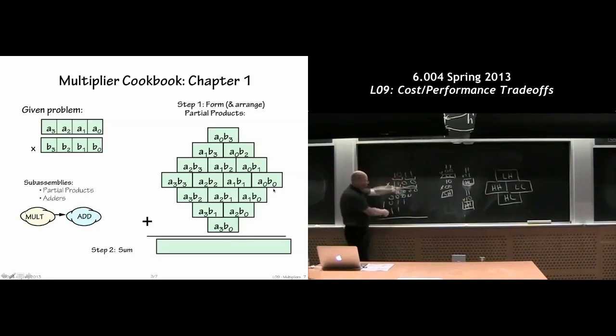I mean, this you learned a long time ago. What was the advantage of arranging things in this way? Well, I hope you can see structurally that if I give you a bunch of n-bit multipliers, and you arrange things in this way, you can quickly build yourself what we call a brick wall of these building blocks to build larger and larger multipliers. And once you have your basic circuit, you can just keep iterating these larger and larger units. It's not like you have to keep designing more and more circuitry.